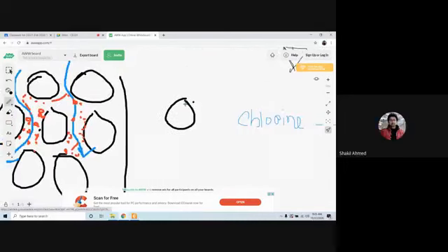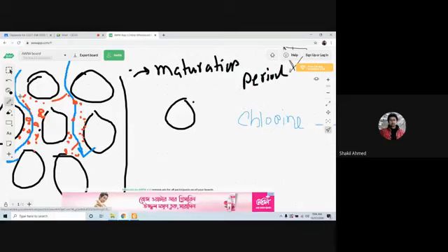So you need to give some time for this media to have the biological film grow on its surface. Once you replace them, you need to give them some days, and that is called the maturation period. That means the formation of the bacterial layer. Maturation period. Is it clear? Yes, sir.